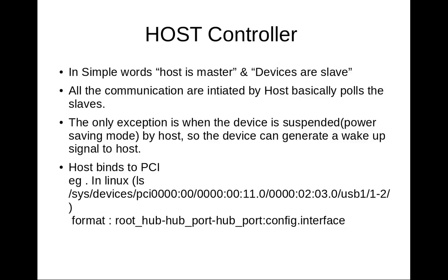Sometimes in suspend mode, suppose your device is doing some transaction and later on you're not using it, so it goes to a suspend state. Once it is suspended, a wake-up signal has to be generated so the host controller detects that the device has data to send, like with network USB devices. Say, for example, you're using a modem.